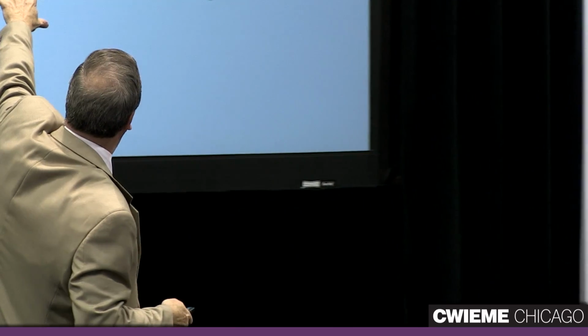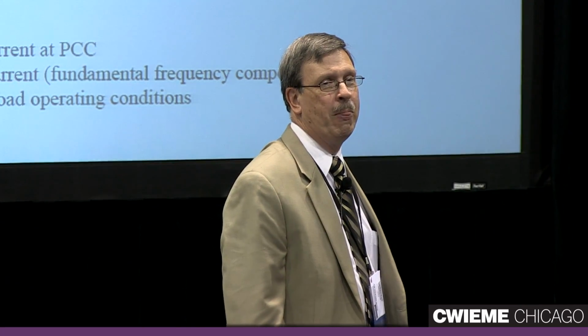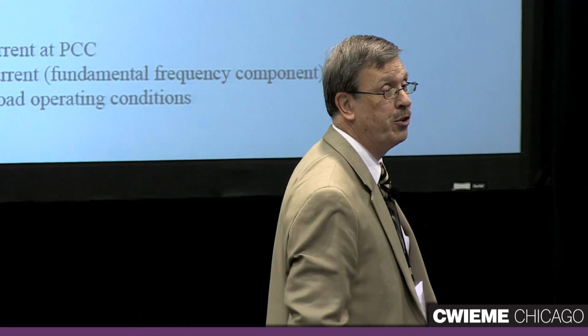And so they have some tables in there that talk about voltage distortion, because that's the key thing. That's what you want to keep low, because that's what affects everybody. And there are some machines that might not work well if you have 10% distortion on that voltage. That's where that problem is. It's not because this drive is drawing so many amps or has 37% current distortion. It's what that's doing to the voltage, and how that is affecting other pieces of equipment. They also have this other table here about the current distortion, because that's what causes that voltage distortion.